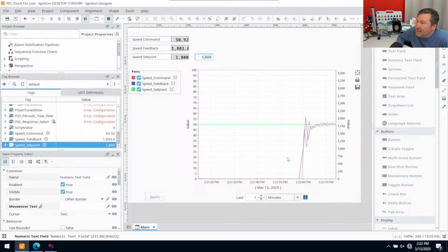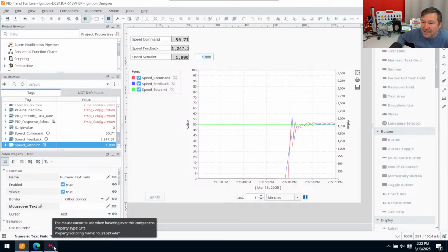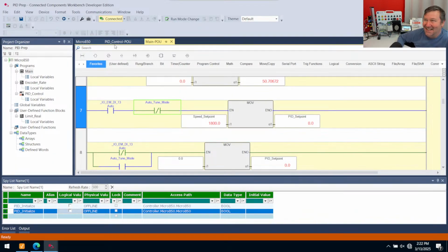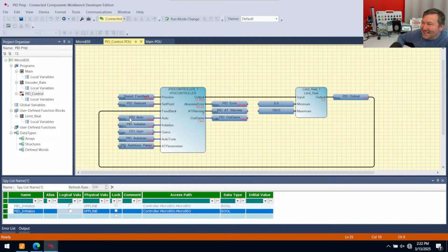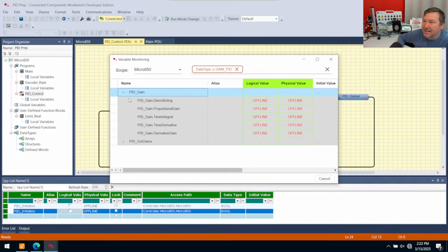But all right. Now you want to know what does the proportional, what is the integral, what does all that do? Then let's take them one at a time. There's nothing worse, especially on a PID, than changing 20 things. But now let's get our gains. We want to know what does the proportional do, how does it affect it? Now this is 0.03. What happens when we make it 0.01?